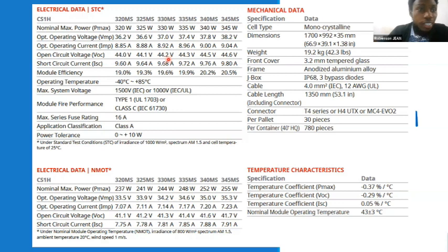And also there is another important thing: the voltage, because the voltage is important to make the coupling with the inverter, because the coupling voltage should be equal to the voltage of the string. Later we are going to see what a string is for those who don't know.